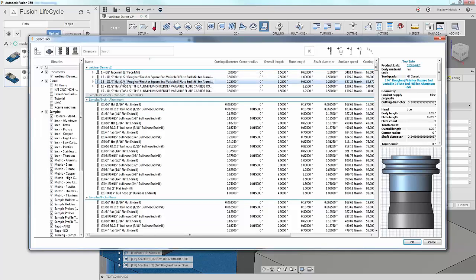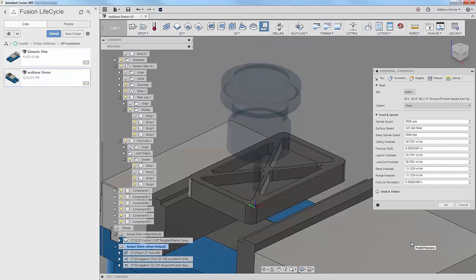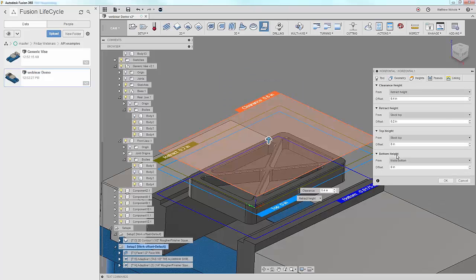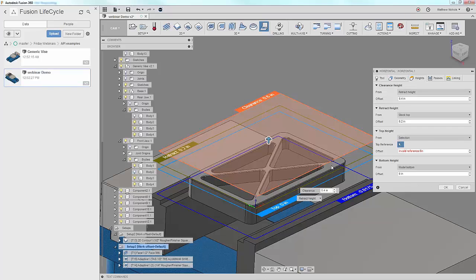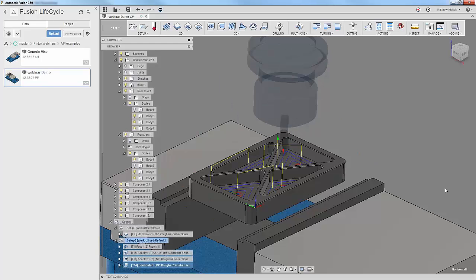So I don't know if everybody's picking up on this, but I think it's an important thing to point out while Matt's adding his toolpath. Oftentimes people think about 2D operations being for prismatic parts and 3D operations being for surfaced swooping parts. The truth is 2D operations are driven off of the two-dimensional geometry you select. 3D operations are driven fully off of the 3D model. And they work very, very well for automating the process of machining even prismatic parts. So if you're not utilizing 3D toolpaths for your simple prismatic parts, I definitely encourage you to do that if you're looking to automate things.